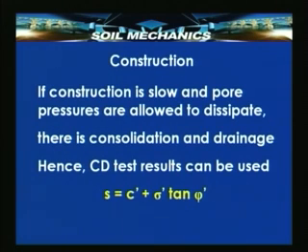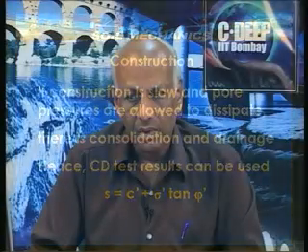It is interesting to note that each one of these corresponds to a different set of drainage conditions, and therefore different test results have to be used. If construction is slow and pore pressures are allowed to dissipate, then there is consolidation during construction and drainage also. Hence, it is a consolidated drained situation and CD test results can be used.